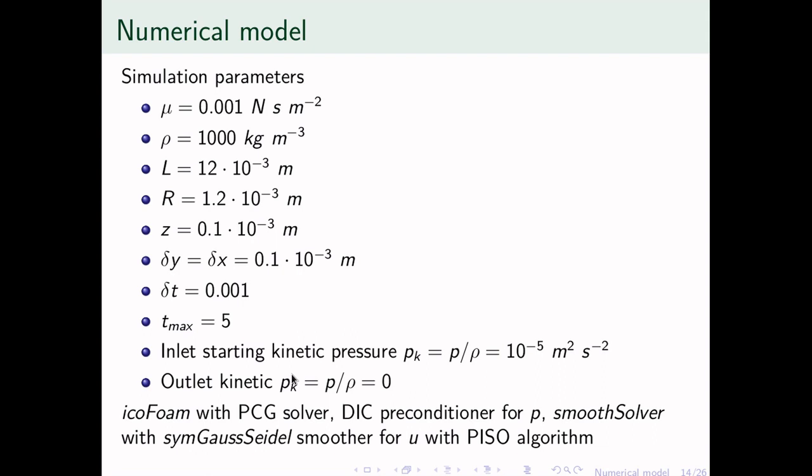Outlet kinematic pressure was fixed at 0. We used icoFoam with the PCG solver, which is the incompressible solver for OpenFOAM, with the PISO algorithm.